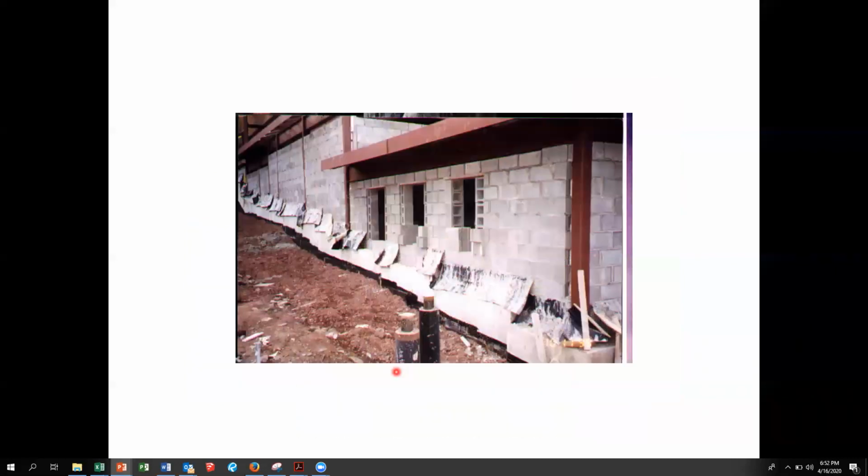There's a good shot of the bump out. Remember that bump out that you folks built on the mock-up of the foundation wall? See that bump out right there? And then there was one on the other side. So here again, you've got block backup wall, insulation, a lot of air gaps in there. And then there's also a bump out of 4-inch block, which is a backup to the brick. These are jumbo bricks, 4x4x12s. Okay.